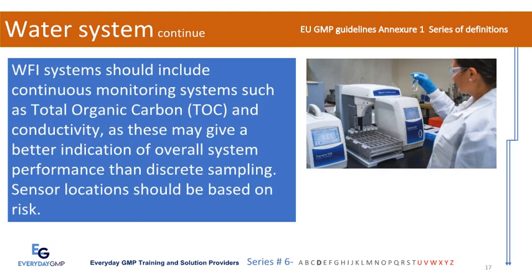WFI systems should include continuous monitoring systems such as total organic carbon, TOC, and conductivity, as these may give a better indication of overall system performance than discrete sampling. Sensor locations should be based on risk.